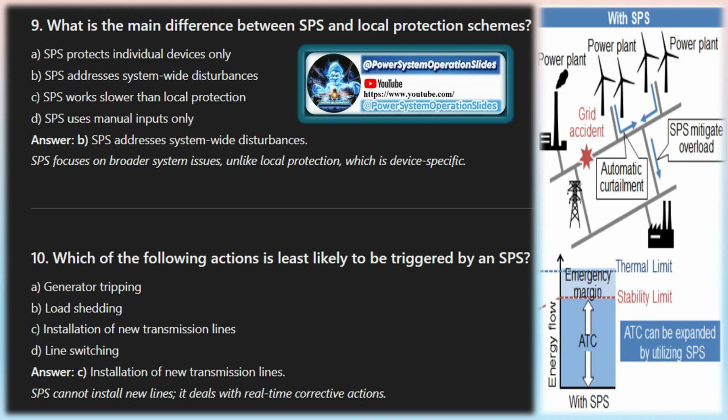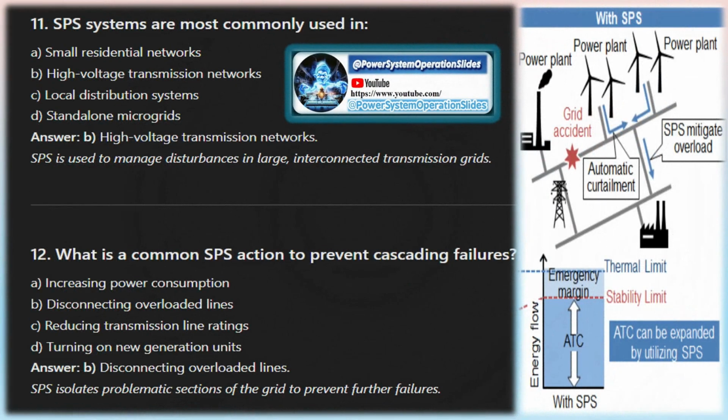Blackout state. A blackout state is characterized by almost total absence of voltage in a certain area of the transmission system as a consequence of tripping of generating units due to abnormal variation of voltage and/or frequency which occurred during the emergency state. Once the system enters the blackout state, the restoration plan shall be activated as soon as possible.